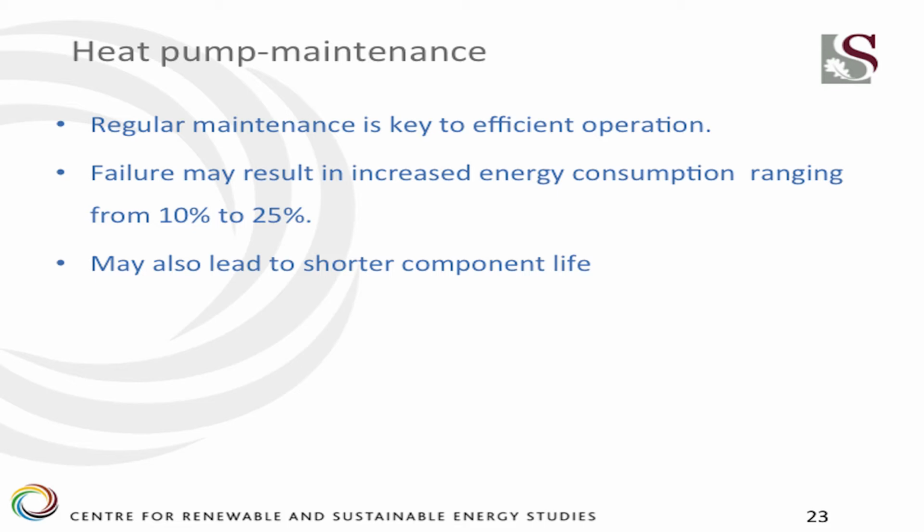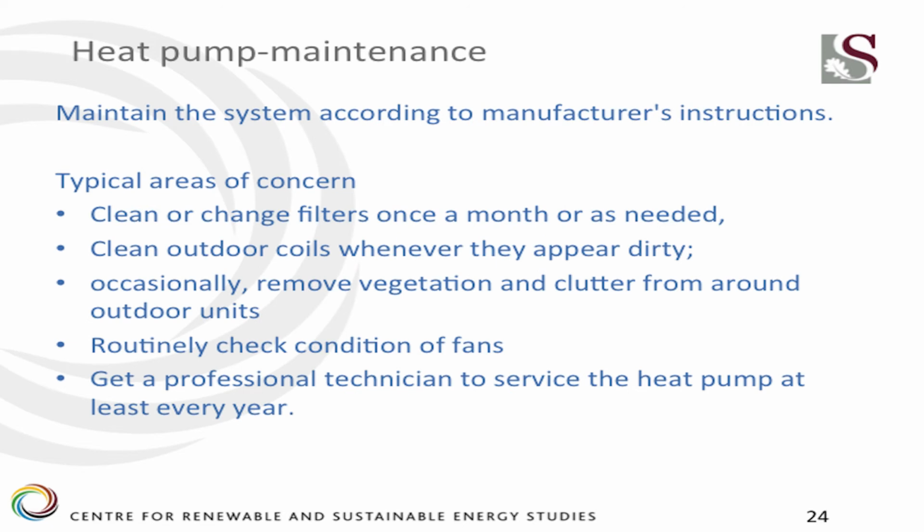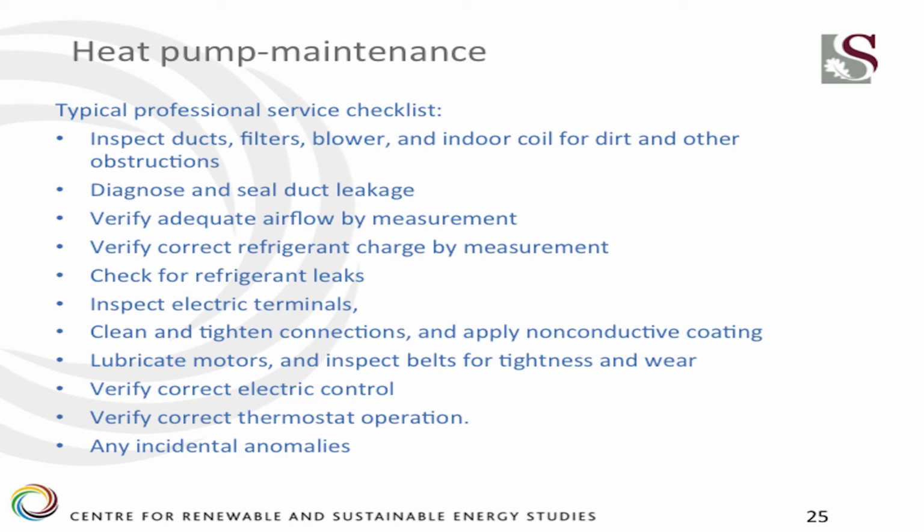Regular maintenance is key, but service providers are the best option for you, and lack of service obviously has problems. Areas of concern: filters, coils, vegetation that clutters around the collectors on the outside, routine checks of fans for jamming, ducts, seals, airflow, using the correct refrigerant, checking for leaks, electric terminals, tight connections, lubrication of motors, verification of electric controls, thermostats, and any incident of anomalies.